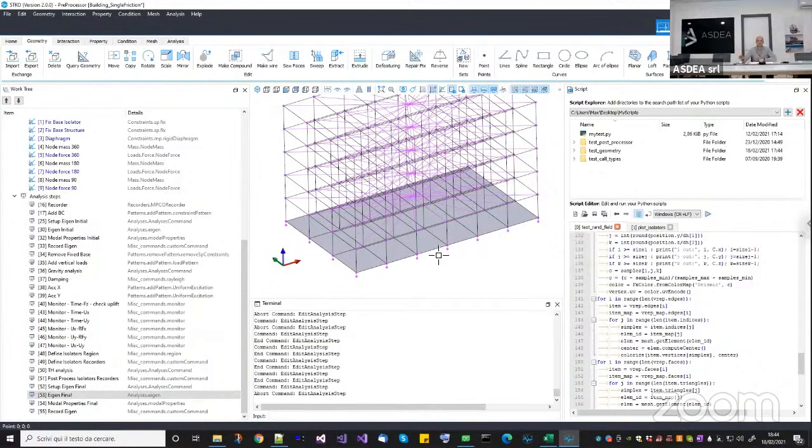But when you are in a nonlinear range, they just contain a bunch of derivatives, okay? So they can be zero, they can be even negative, for example, if you have softening. So they lose their physical meaning, and so to me it does not make sense to run an eigenvalue analysis on a nonlinear model, okay?